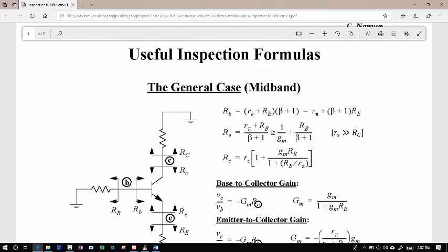When you see a resistor in a circuit, what are you thinking? You're not thinking, oh, okay, there's a current source here, there's a GM there, there's an R pi, there's an R. No. You're thinking immediately, okay, V equals I times R. You know that immediately. That's what I want you to be able to do with a transistor. With a transistor, I don't want you to see a transistor and say, okay, let's see, the hybrid pi model is this. That's what I see for the transistor. I want you to see its terminals and to see the resistances in those terminals immediately. To see the gain across those terminals immediately. See it by that symbol, not by a hybrid pi model.